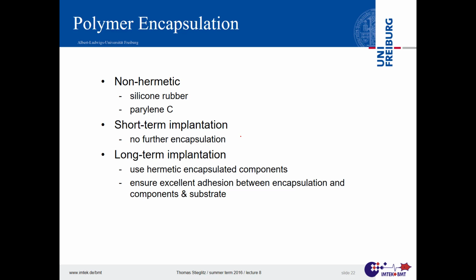And the epoxy was not very pure, and if you look up old literature in databases, which is now digitized, from the 70s you find something like pacemaker dermatitis. That means there was skin erosion at the place where the pacemaker was implanted. The reason was that the epoxy had toxic leaching agents that came out and destroyed the skin. And Parylene C was an awesome material. You could coat your epoxy pacemaker with Parylene C, and by that you prevented the leakage of toxic agents into the body.